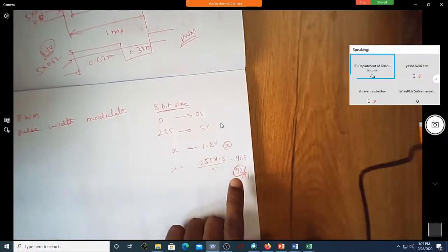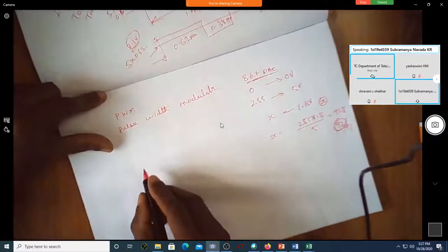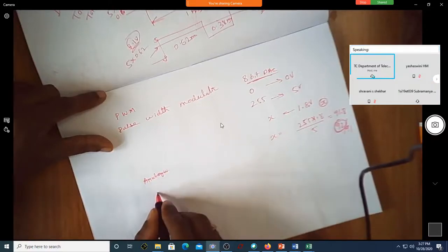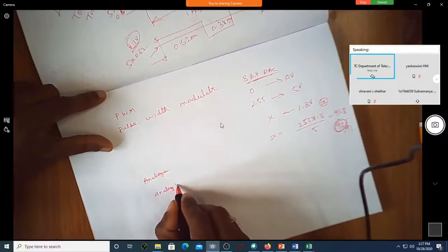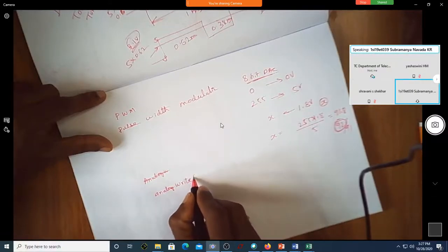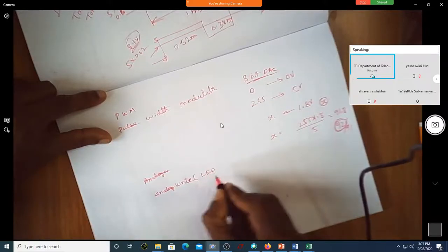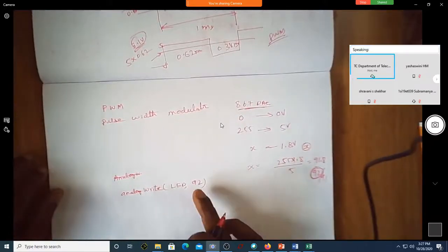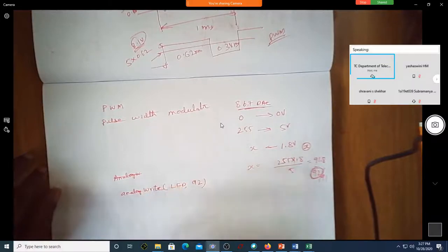So I need to write this analog value. In the statement, I'll use analogWrite to a pin, let me say LED, with 92. Then this 92 will be written onto this LED as an analog value.